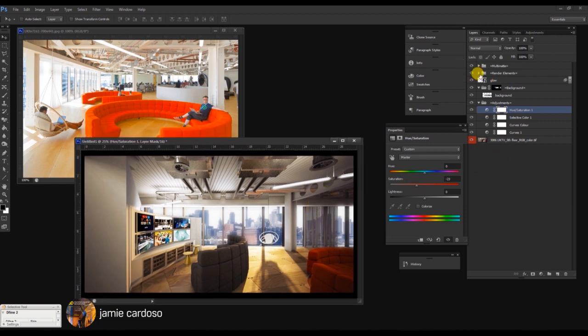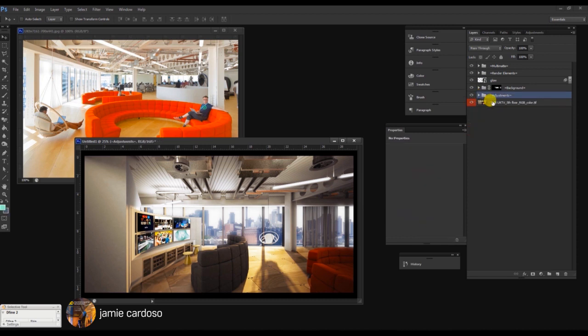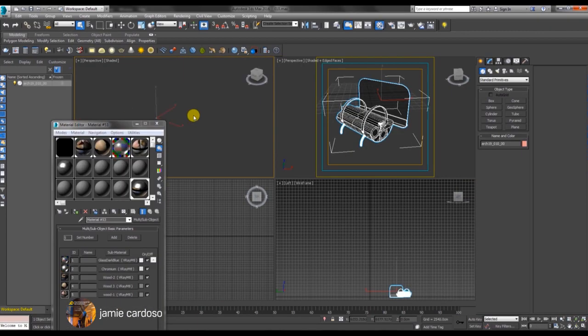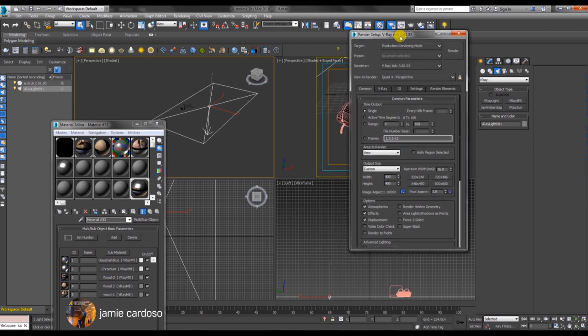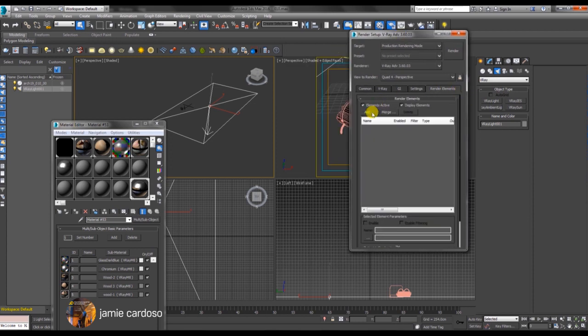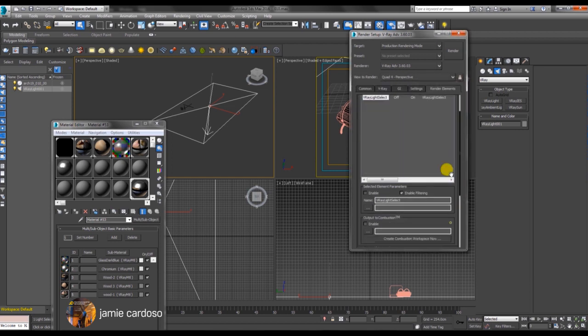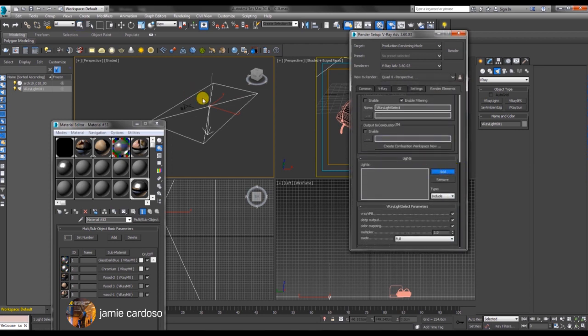And the next thing that we're going to do is to start playing with the lights slightly. The one element I really enjoy playing with is the light selection tool, the V-Ray Light Select tool, which is quite good. To actually apply the V-Ray Light Select, you simply create your light in the scene. You open the render setup, go to Render Elements, Add, and just select the V-Ray Light Select tool, and then scroll down, so you just add a light.